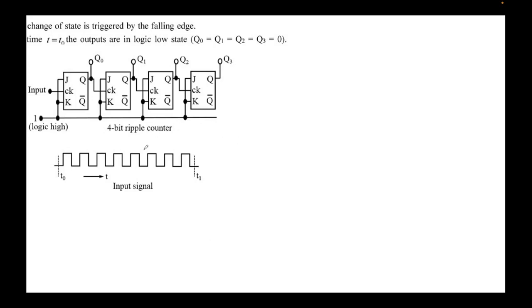This is the circuit diagram. I've just drawn it again. Now let's forget about anything and just look at the output of Q0. So I'm writing the truth table for this JK flip-flop. I'll write J0, K0, and the output, let's say, Q0 n plus 1. Okay, this means the n plus 1th state. And we know this is 1. Right? Because both the inputs are 1, I know that the value will be Q0 n toggled. So whatever the previous value is, the next value will toggle.